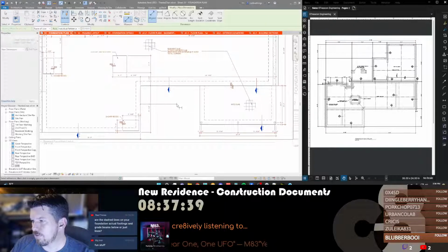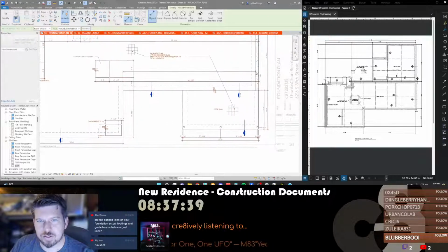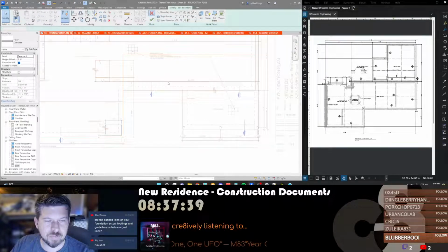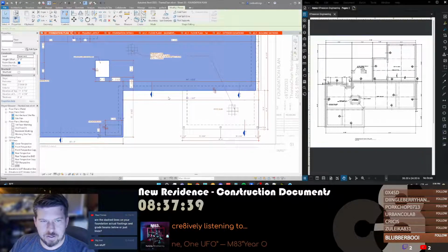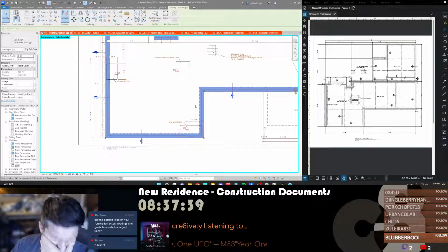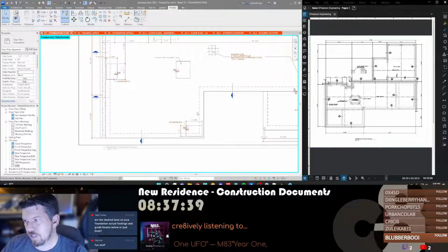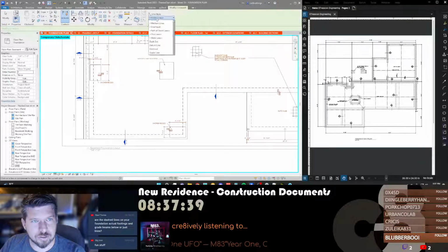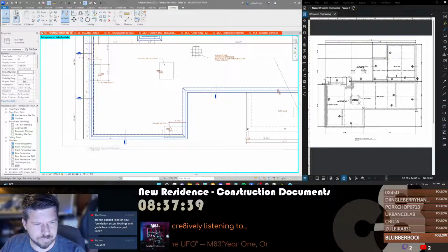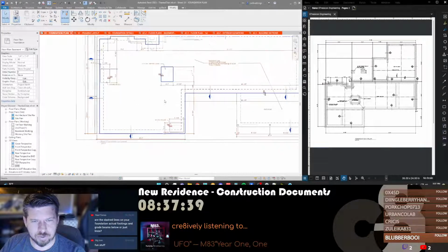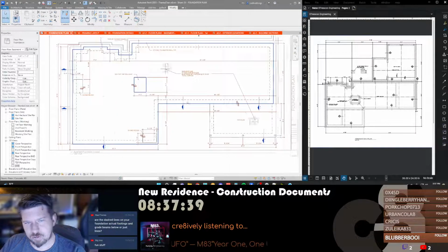Dash lines on the foundation, actual footings and grade beams below, or just lines? A little bit of both, actually. In this case, these are the actual footings around the perimeter of the slab. And I use the Lineworks tool with hidden lines to get where it hits. So when the floor is on, it still shows up using the Lineworks.